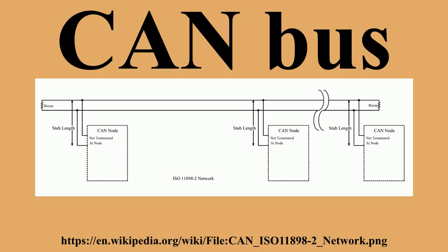A terminating bias circuit is power and ground provided together with the data signaling in order to provide electrical bias and termination at each end of each bus segment to suppress reflections. Data transmission: CAN data transmission uses a lossless bitwise arbitration method of contention resolution. This arbitration method requires all nodes on the CAN network to be synchronized to sample every bit on the CAN network at the same time. This is why some call CAN synchronous. Unfortunately, the term synchronous is imprecise since the data is transmitted without a clock signal in an asynchronous format.